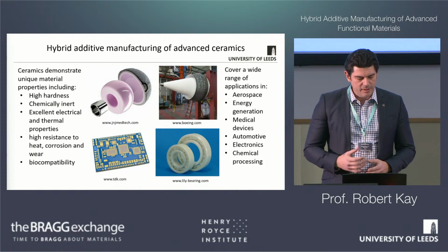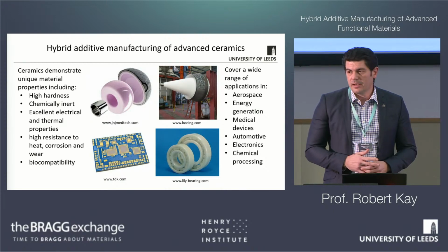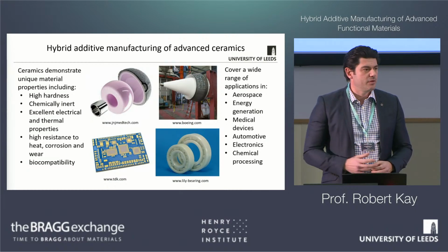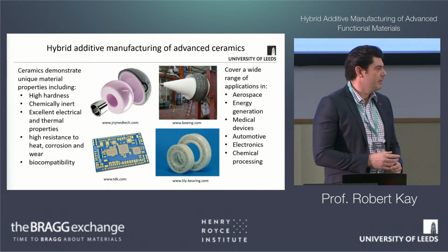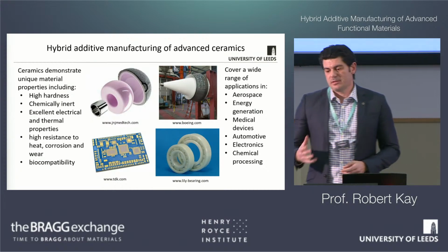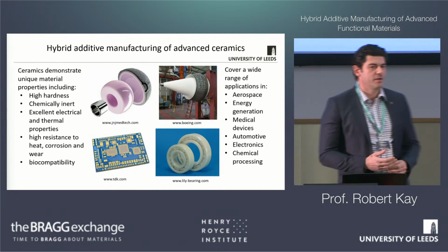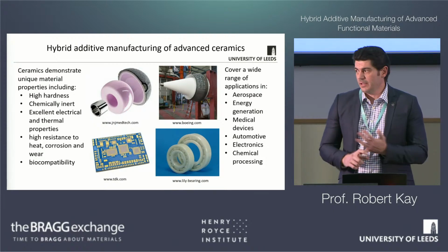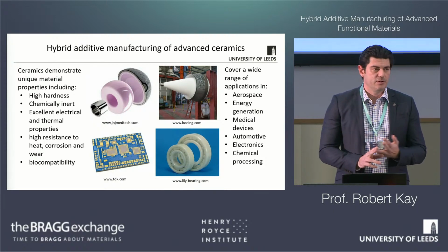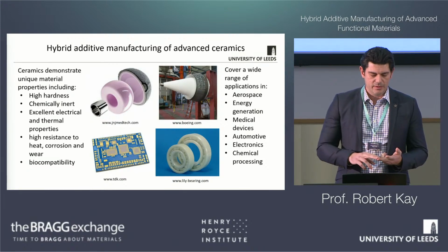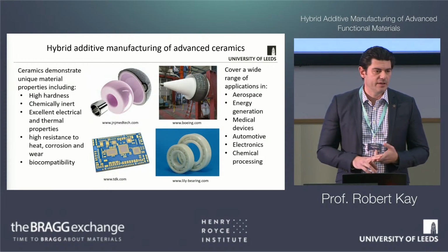Okay. My other example I wanted to cover today was on additive manufacturing of ceramics. Now, if anybody looks at 3D printing ceramics, what they found is that people have taken metal and polymer processes and they've adapted them to print ceramics. And what that's done is it's created a lot of trade-offs for most industries. So there's certain materials you can't process. You quite often have to change your feedstock formulations. Quite often there's higher issues around things like higher porosity, higher shrinkages.